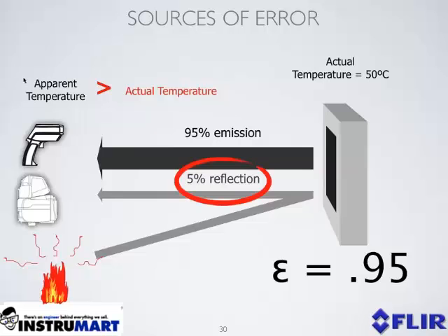Herein lies the challenges with infrared thermometers. The infrared thermometers I used in my experiment had no input value for T reflection. This creates an inherent difficulty in using an IR thermometer when making measurements on targets that are not perfect black bodies, or making measurements on targets that have emissivity values less than 1. There is no way for me to compensate or adjust for the temperature of that reflected radiation.